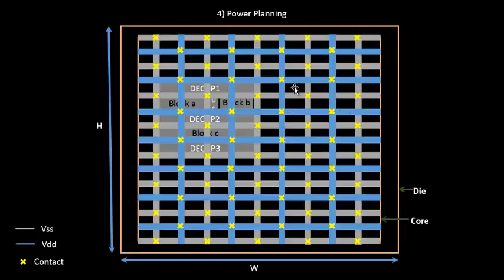All these things have been covered in greater detail in the crosstalk videos. You might want to have a look into them, where we explain when this kind of situation might arise. This kind of situation might arise when, let's say, thousands of logic gates are charging from 0 to 1, and they demand current at the same time.